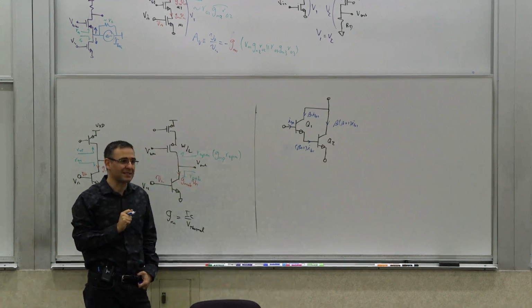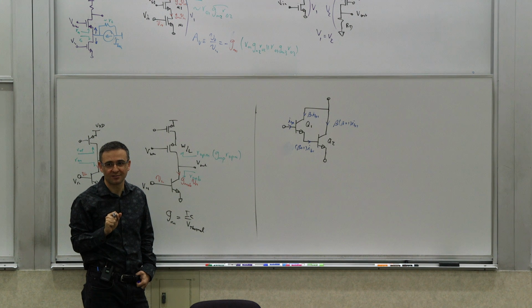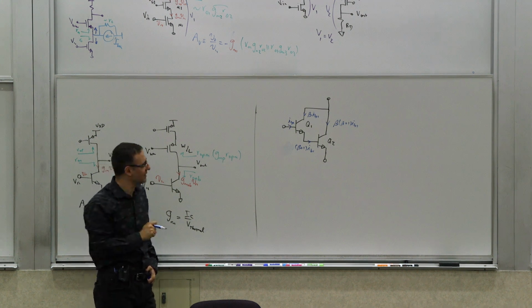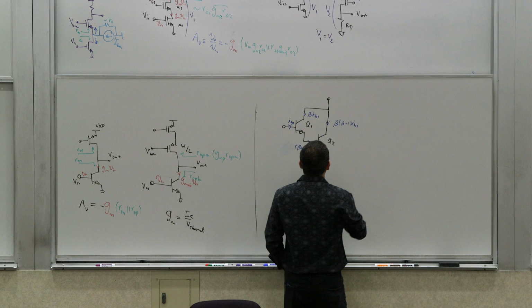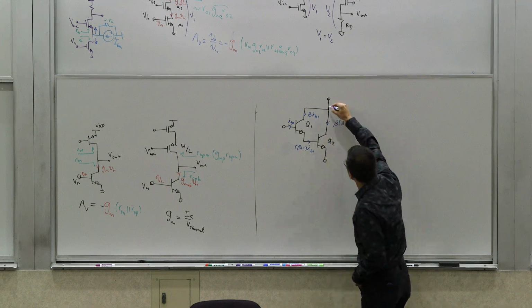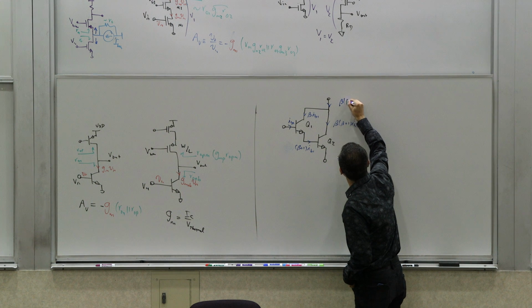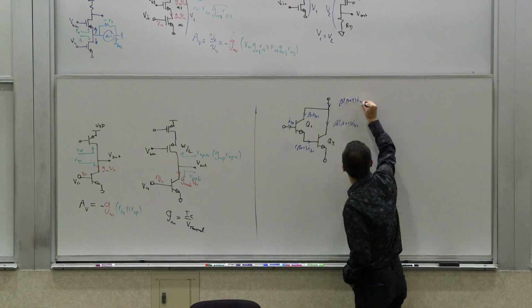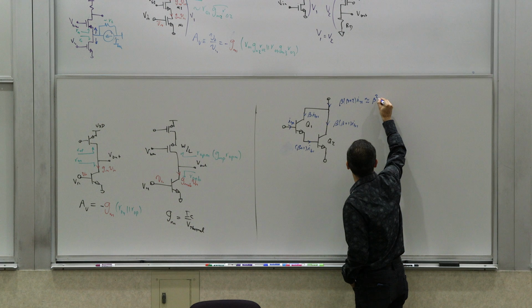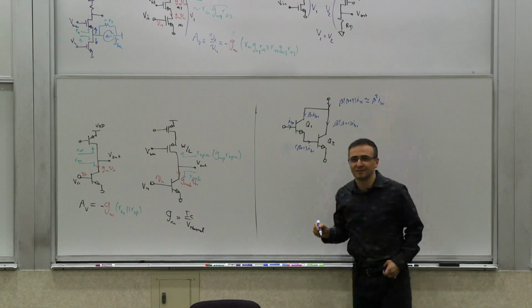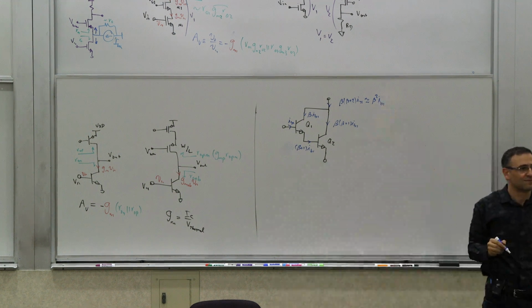which may not be the case, even if there are similar transistors. And I'll ask you why in a few seconds. Just think about it. But then the total current here is basically what? It's beta times beta plus 2 IB1. It basically essentially is beta squared IB1. Right?